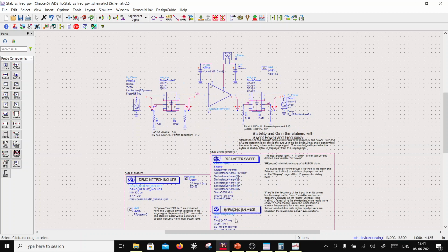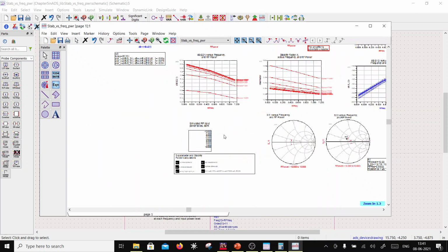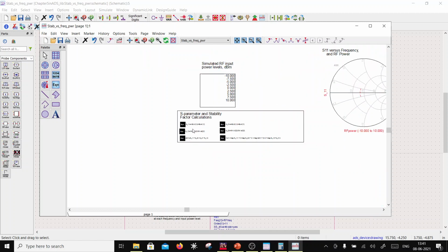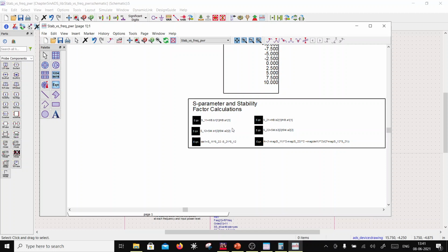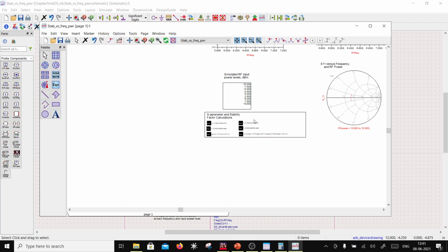So what's the difference between computing over here versus computing in the data display window? So what happens is, if you want to have different data sets and you want to apply the same formulas, you will not be able to do that if you write the equations in the data display window. Had you written these equations in your measurement equations, then whenever you change something, for example here, and store it to a different data set, all these computed values will be available here.